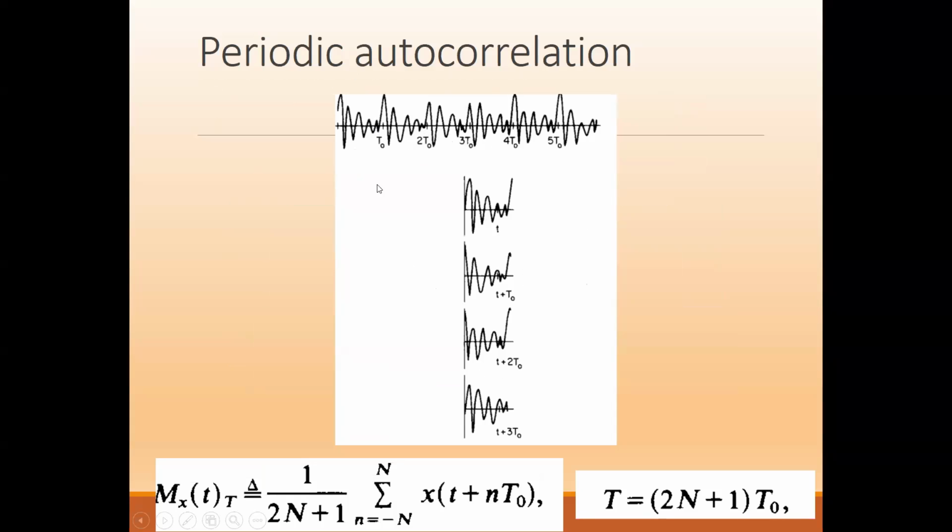So suppose you have to pass it through a band pass filter of say 0 to 1 megahertz, you take a particular value of T0 and do the operation. Now I want to compute say 0 to 3 megahertz, have another value of T0 and do the processing. So by changing the value of T0 with which you are computing the autocorrelation, that is equivalent to passing the signal through different band pass filters. By doing that, what actually are you getting? Let me show you one thing. Now let me come back to this part.